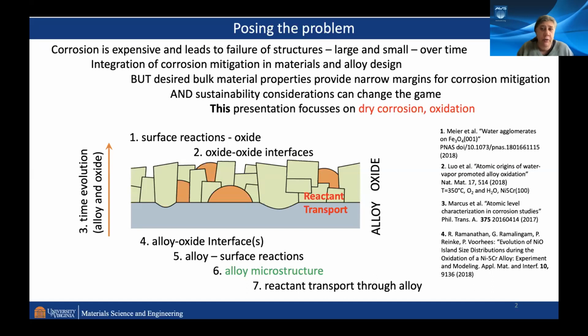So we'll also focus on the oxides. In general, that should be a dense oxide. So the best candidates are always chromia, alumina, and sometimes silicon dioxide. Those are dense oxides which don't dissolve well, but all of them at some point will volatilize. So if you go to very high temperatures, your boundary conditions change again.